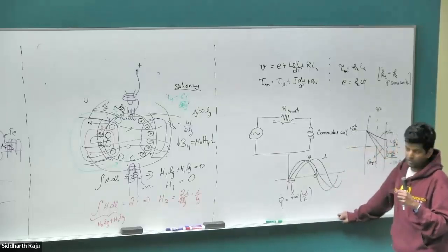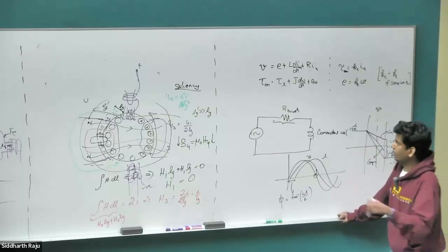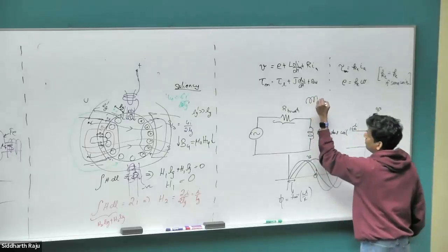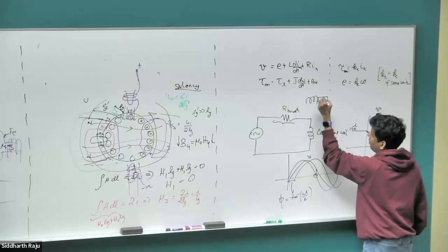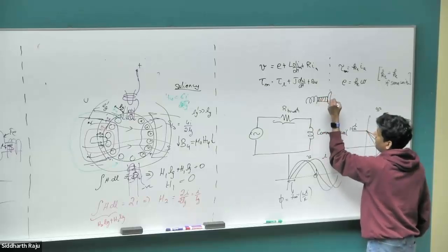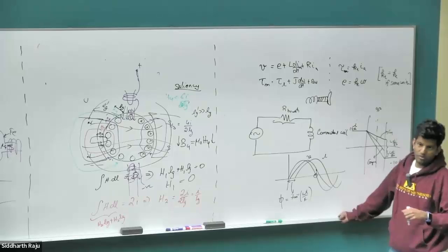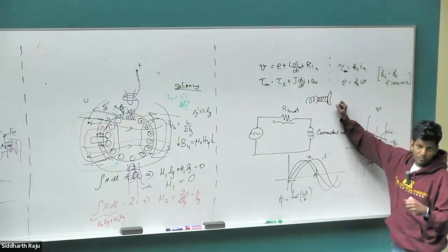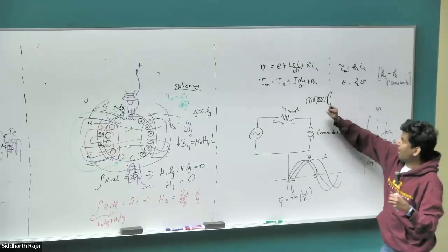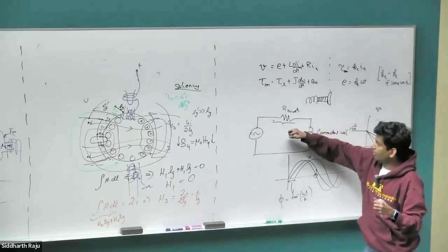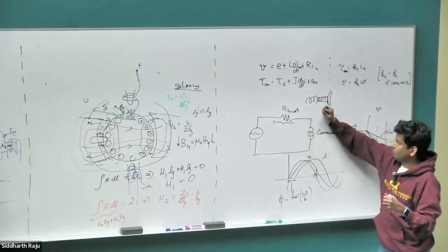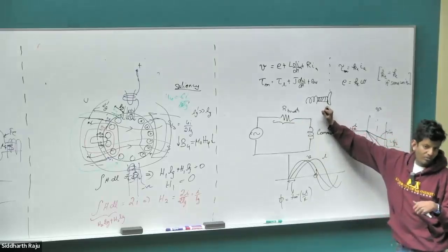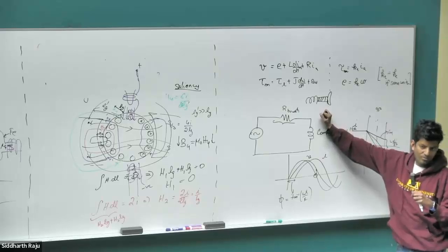Copper also wears out. In both these cases, what we do is we put the commutator segment, brush segment on a spring that keeps pressing against this copper brush that we have. So even when you have the copper brush, the spring would keep pressing against it and it will still keep making contact. And the wear out rate of the copper brush is lower than the graphite brushes, but it's not appreciably lower to make the justification. And what is the biggest problem with having the graphite brush?